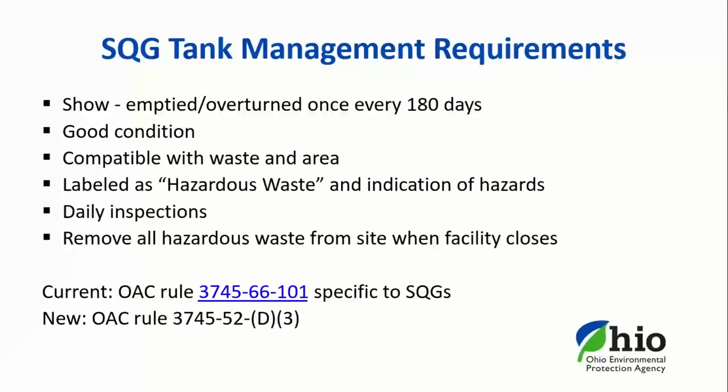The tanks need to be labeled as hazardous waste and an indication of the hazards. The tank structure needs to be in good condition and made of a material that's compatible with the waste. The discharge control equipment and data gathered from monitoring equipment, such as the pressure and temperature, needs to be inspected daily.